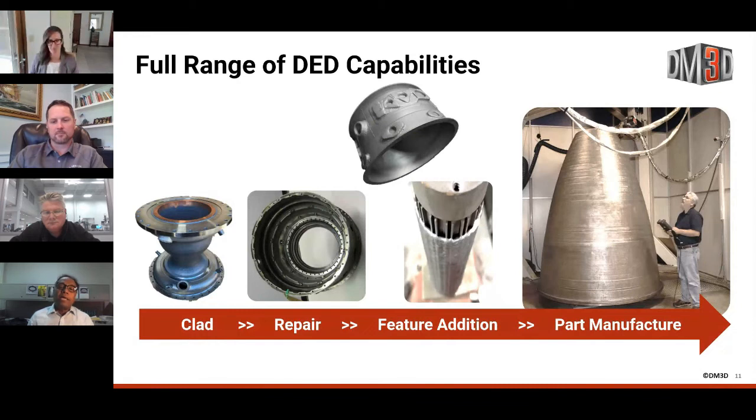Now, repairing this kind of parts and repairing used parts is a little bit different. Used parts are already in finished condition. Their own microstructure is already there. Parts have very tight, finished dimensions. So during repairing used parts, you've got to be really, really careful about stresses, distortions and thermal conditions.